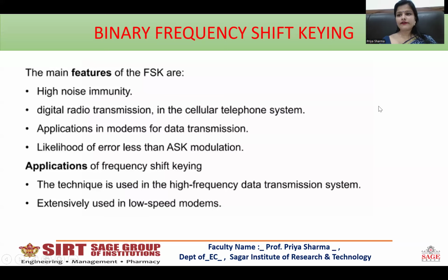The main features of FSK are high noise immunity, digital radio transmission in cellular telephone systems, application in modern modems for data transmission, and likelihood of error less than amplitude shift keying modulation. Its applications: the technique is used in high frequency data transmission systems. It is extensively used in low speed modems.